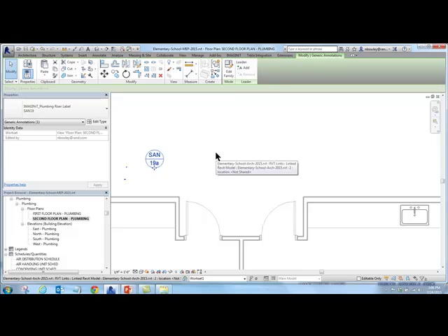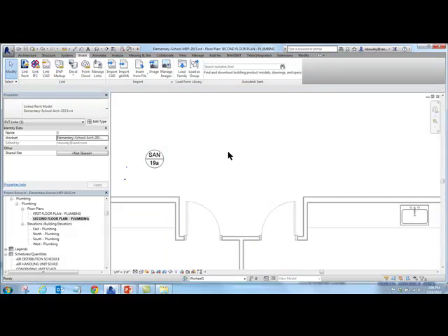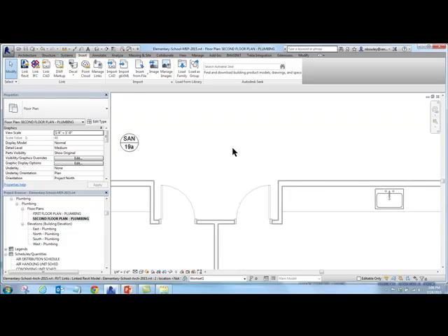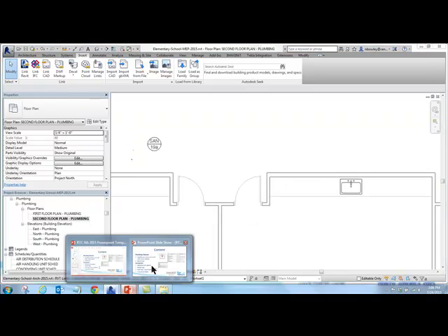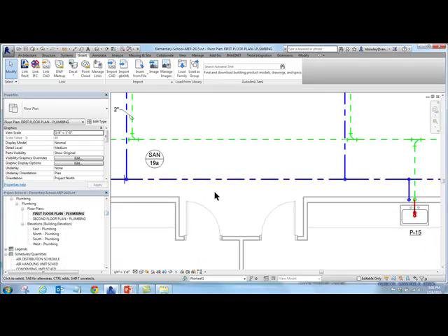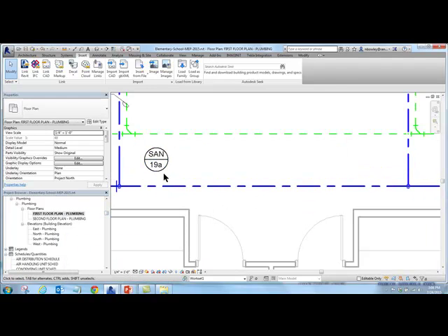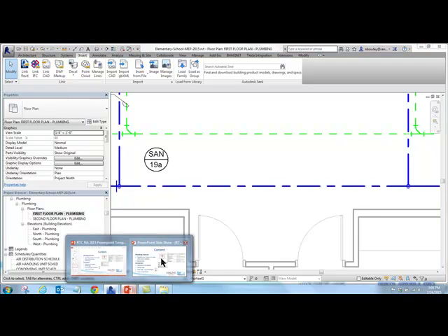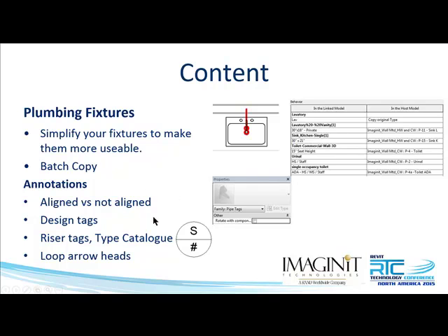It's not really as intelligent as other things in Revit, but it works. It's still a dummy tag. It's just still saving me from a lot of manual effort when somebody decides to change the numbering system. So it might seem simple, but if it comes up later, you're gonna be grateful. If I go back to the first floor just to verify, that says 19A as well. So if that was a 100-story building, you've updated 100 tags. Simple concept, but hopefully a creative use of a simple idea.